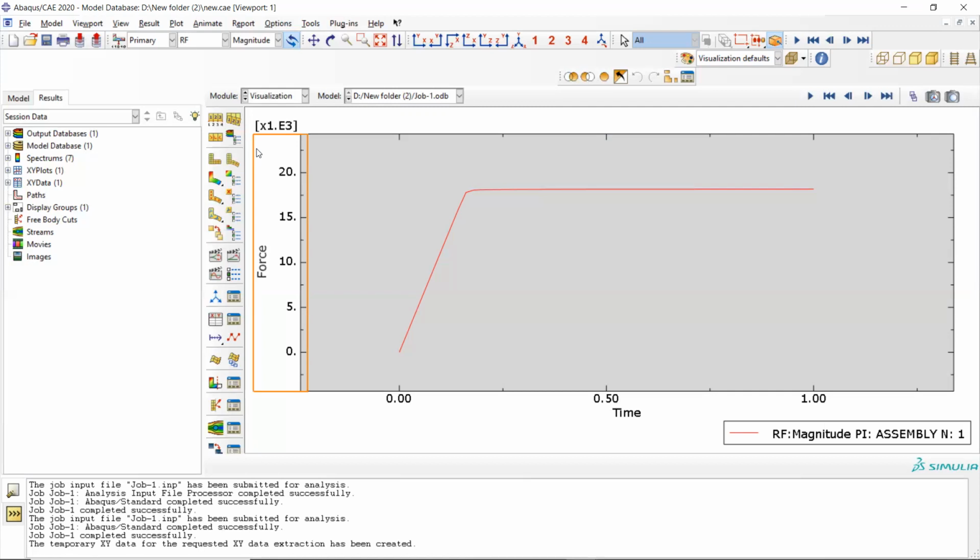The stiffness is calculated by the software and multiplied with the displacement value that we give, and then it will calculate the force. But if you give the force as a value, then your force matrix has to be divided by your stiffness matrix. So sometimes matrix division is a challenge, that's why it's throwing up errors.